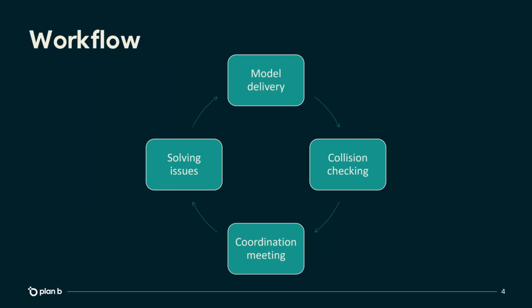In the project, we had a workflow where we had model deliveries to BIMsync, which we used as a BCF and IFC server. Then the models were synced into Solibri, where I, as a BIM coordinator, could perform collision checks. Then I created issues that I synced up to BIMsync. Before the coordination meeting, all the designing parties could review the issues, and if we had any important issues to discuss, we could tag them, so we had really good meetings. The coordination meetings were held in BIMsync, so everyone could access the model and the issues there.